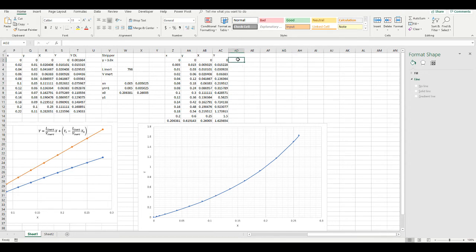So to do that, let's first take into account the operating line equation. While we don't know the flow rate, we're going to have to guess different values of the flow rate, until we find one that gives us exactly 4 stages. The final exit concentration will be given by where the operating line passes through once we have the correct flow rate. So we're going to first take the operating line equation and simply use the inner gas flow rate, and then we're going to iterate until we find something that works with 4 stages. And this will just have to be done manually because we have to trace the McCabe relationship by hand.